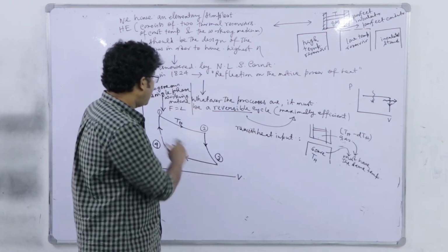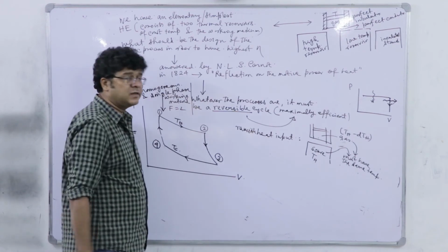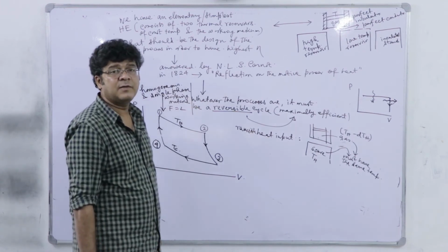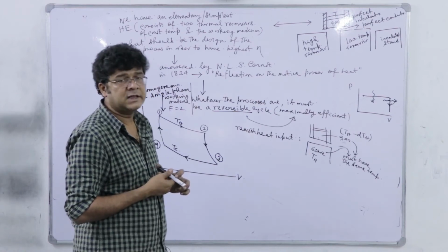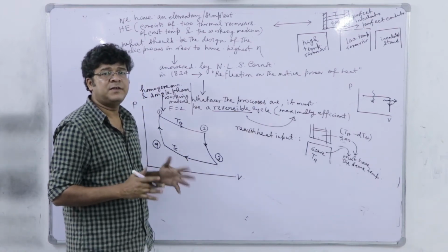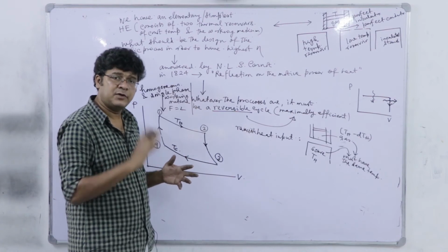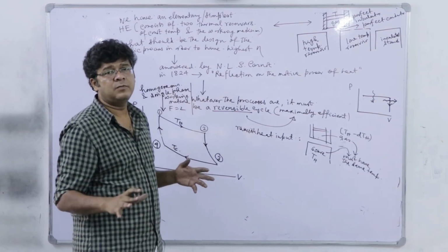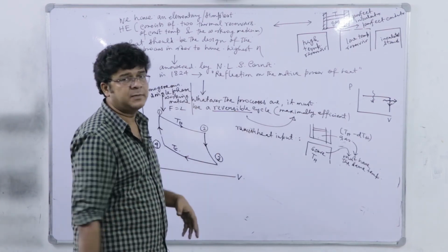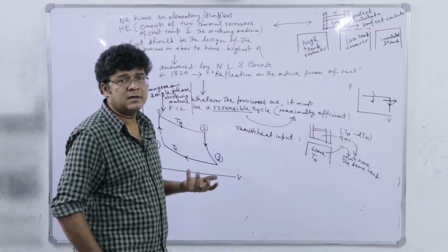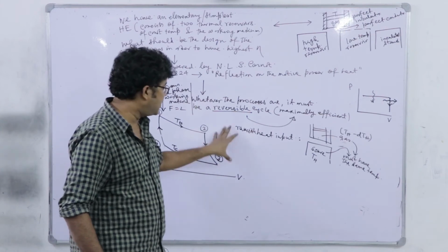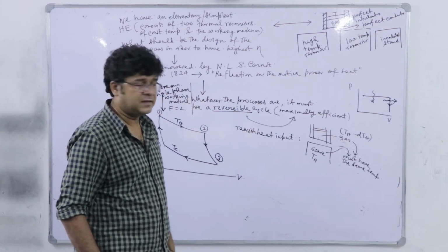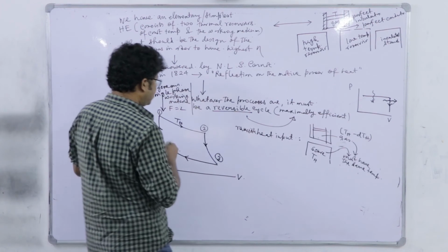So, with this reversible cycle, here we are going to prove this Carnot cycle efficiency to be 1 minus Tc by Th, and as we have not been introduced to the concept of entropy, here we have to consider some working material, and that will be ideal gas. However, the Carnot cycle efficiency is universal. We will see later, when the concept of entropy is introduced, that we can prove this efficiency to remain invariant, what we are going to prove here with this assumption of ideal gas.